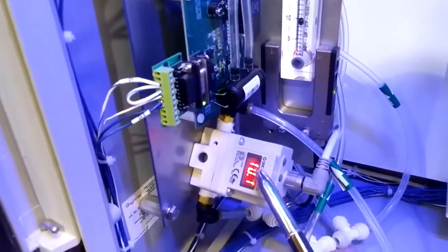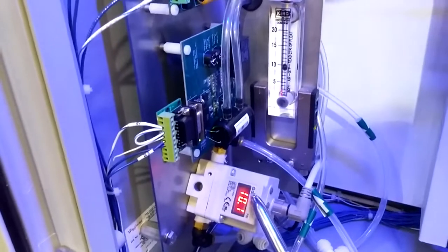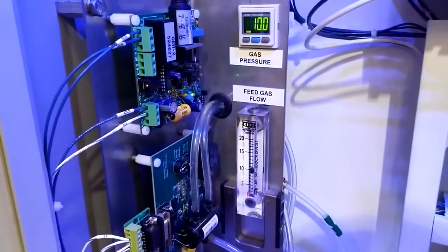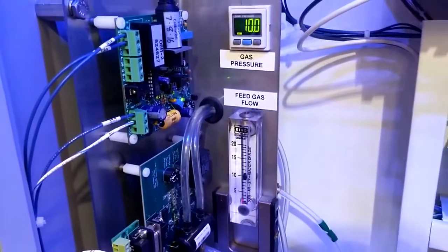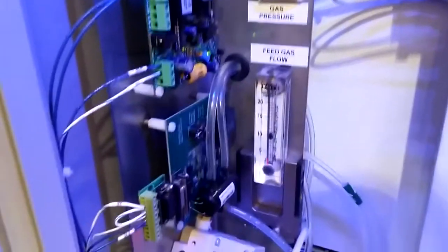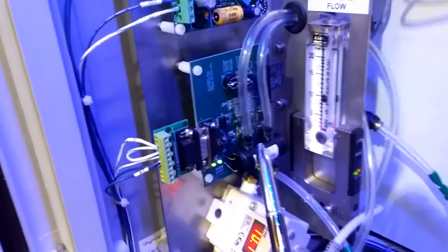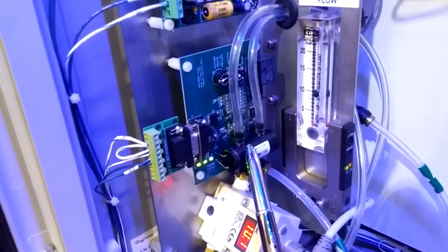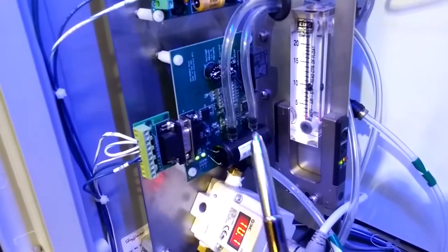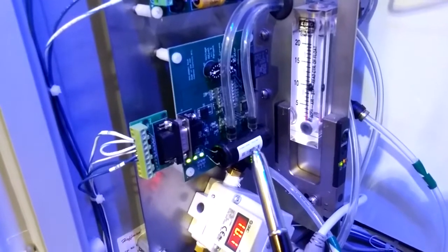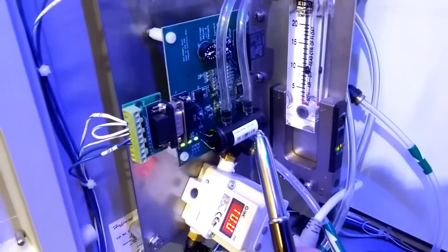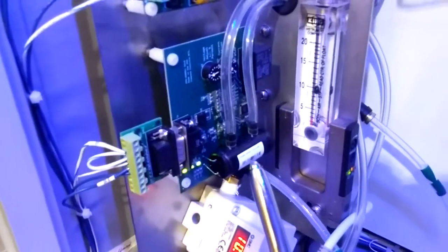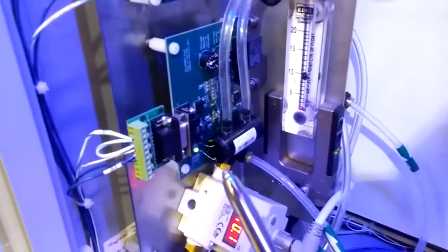The nice thing about this electronic regulator is that anytime gas flow is adjusted to the system, it will automatically readjust itself to maintain constant gas pressure within the limits of its feed gas supply. Over here you see we have our oxygen monitor. This monitors the feed gas quality and gives us our concentration indication on the HMI as to what our current percentage of oxygen is. That would help us to detect if there's a problem with our oxygen concentration. If feed gas quality is poor, we'll know it by this monitor here.